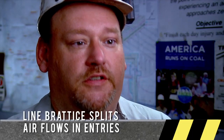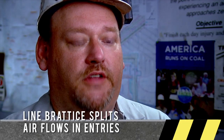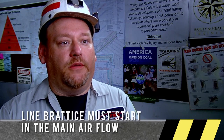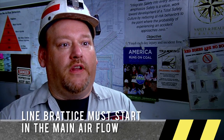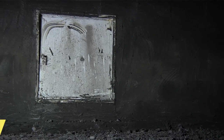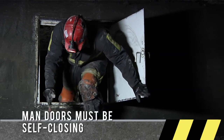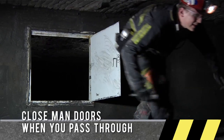A line brattice is just like a check curtain. It directs the air, except it splits the heading longitudinally, so we can direct the air to a specific spot, like the face in a mine. The problems with a line brattice are, most of the time what we find is they're not brought out into the main airstream current enough to move enough volume of air to the face of the mine. It is against regulations to leave a man door open because that does affect the whole ventilation of the mine.